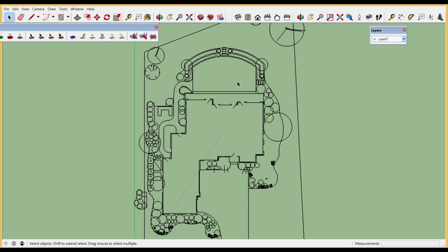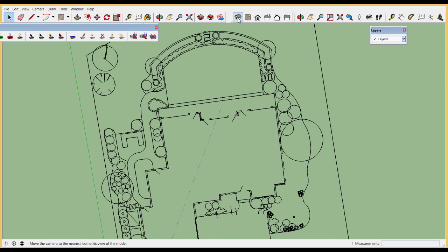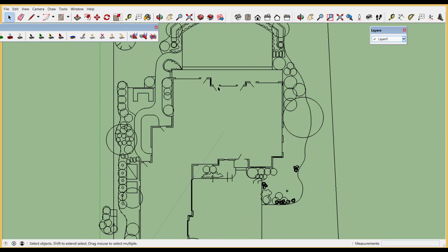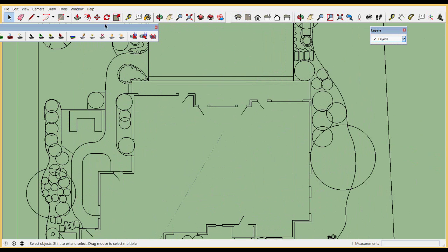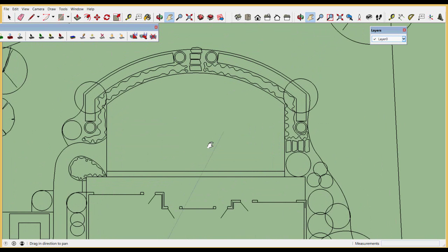So now we can use the tools within the SketchUp environment to build a 3D model based on the base geometry. Let's zoom in and I'll pan down a little. There's my pan tool, here it is. So let's look at just this back area here. What I'll do is put down a rectangle from, say, that point there to that point there, and just putting that one rectangle down, in fact, brought a couple of surfaces or more than that. We've even got this little block of perennial planting appearing. So that was just one click.